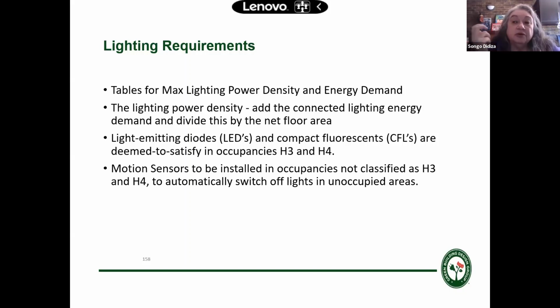So the CFLs are generally 10 to 11 watts as opposed to a 60 watt light bulb. And that obviously is just lower energy. So we're saying the right kind of lighting must be there, but just do it at a low power or low energy requirement. In the new 10400XA, what it says is that in housing, if you've got LEDs or CFLs, you're deemed to satisfy.